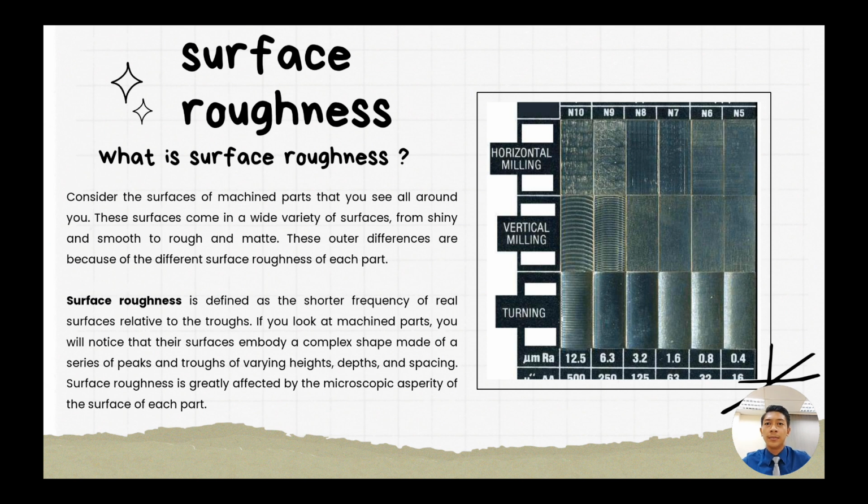In CNC machining, the surface roughness influences how the manufactured part will interact with the surrounding environment. A typical CNC machining finish as machined is smooth to the touch, but will contain visible machining lines from the cutting tool. This level of roughness is suitable for most parts.